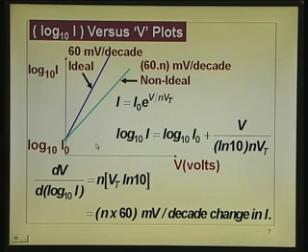Now, to find the slope in this semi log scale, what you do is differentiate this with respect to the whole term itself. So, delta V divided by delta of logarithm of base 10 I. When you do that, this term goes off because it is a constant, it does not vary with voltage. So, this particular quantity now becomes V by n V t.